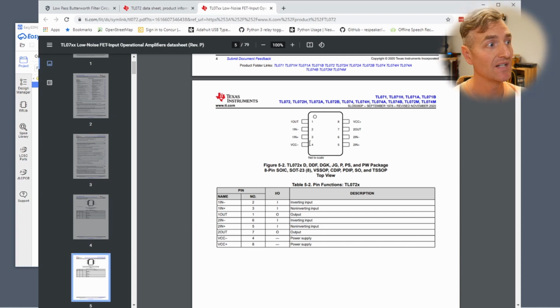It doesn't work that well. So I need to make sure that if my signal goes below ground, the reference level for my op-amp is also below the ground. So how do I do that? That is a great question because all I have is one 12-volt supply. And what I really need is a positive 12-volt supply and a negative 12-volt supply referenced to a single ground plane. One of the cool things that I can do, though, is use some passive components to split it up.